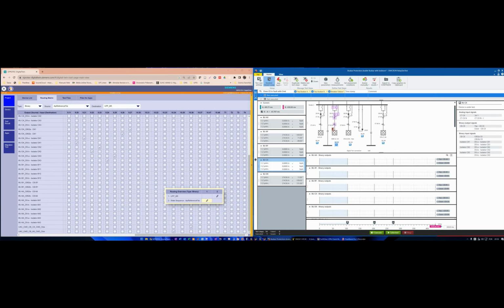We put a step normally, and this fake circuit breaker is open. This real circuit breaker is open too. Here we apply the fault, but this bay is open, so there is no current flow here. And here we created a command in our fake circuit breaker. So I give this command, and this command looks like a close command to my bus bar protection.